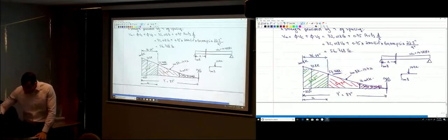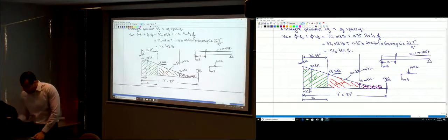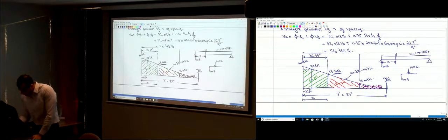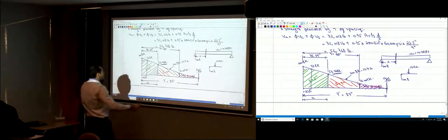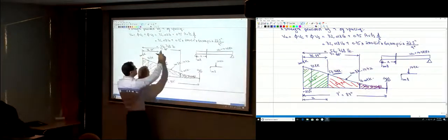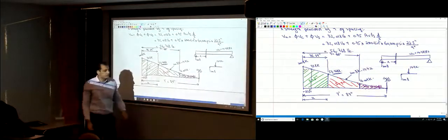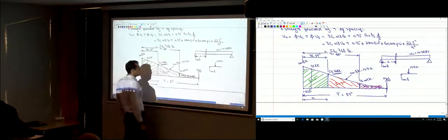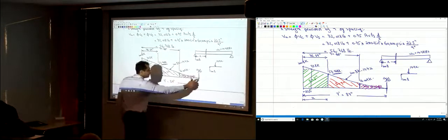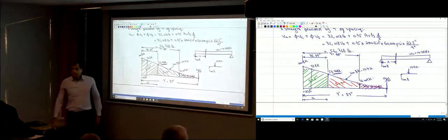So that distance from the beginning is 70.66 inches to that point. Subtracting those two values, you can know this distance, 70.66 minus 36.7. That's the distance where you need number 9 stirrups, and then here you don't use stirrups. Okay?